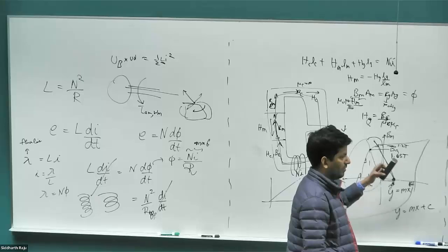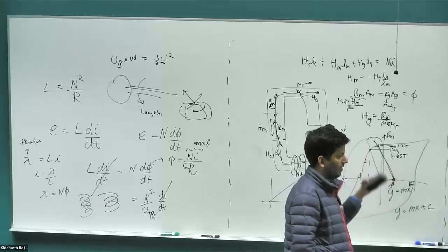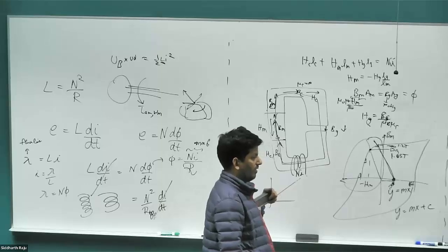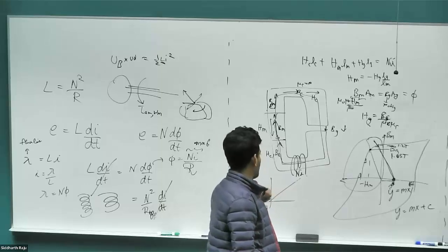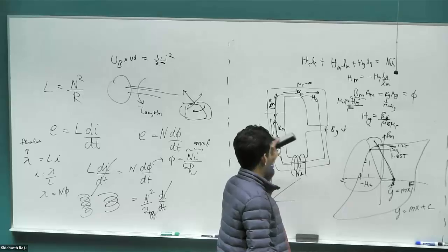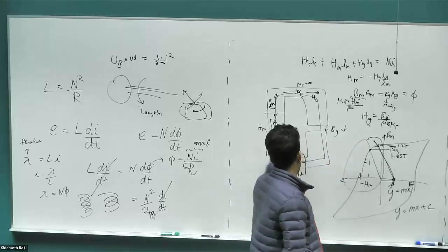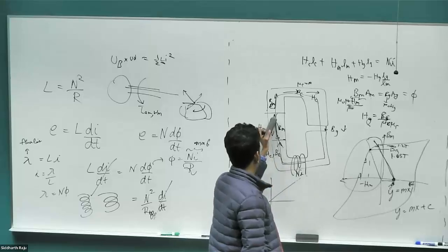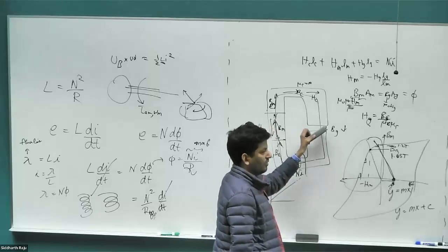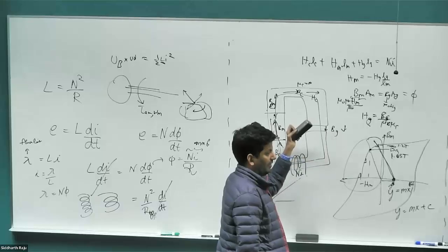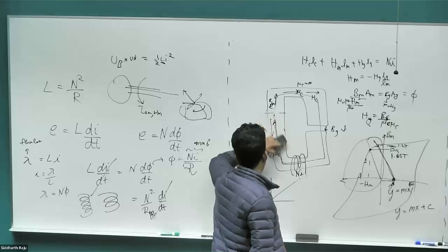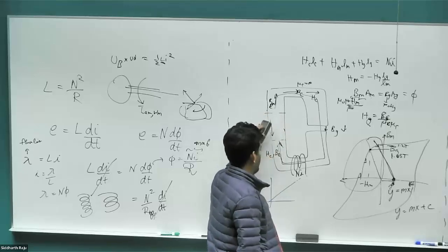Okay, yeah, because it would just make sense to take the magnet out and just put the coil with the current. The point of this is to make a constant magnetic field in the air gap, right? Yep. Yeah, because the magnet actually, as I mentioned, the neodymium magnet behaves like an air gap. So when you put an external coil, this magnet appears like a large air gap added on this air gap. So if you're creating a magnetic circuit with an external conductor, it would make sense to make this completely iron, because this offers a lot of reluctance.